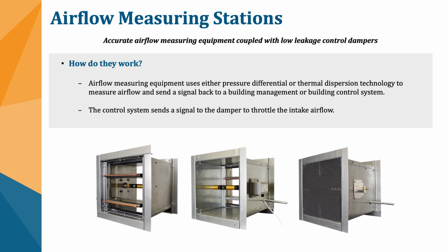And it's using that to calculate the differential pressure between the actual airflow in the duct and the static pressure that's in that system. The thermal dispersion units are a little bit different in that they use an encapsulated thermistor, or some device that has a different resistance over a different temperature range, along with the heater. And that gets calibrated a specific way where you've got a known airflow through another calibrated orifice, and you can then figure out how much that airflow reduces that temperature, or how much electricity has to be put into that little heater next to the thermistor to create a constant temperature. And you can use that to figure out airflow.